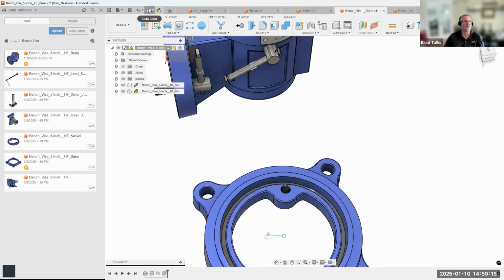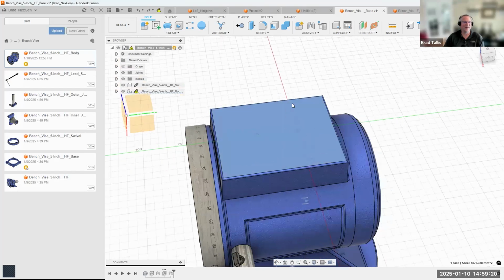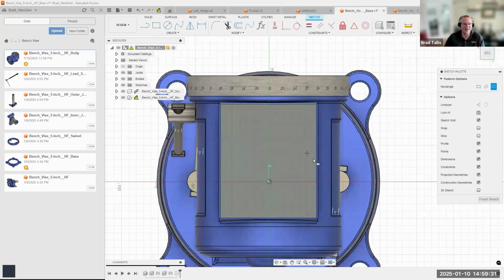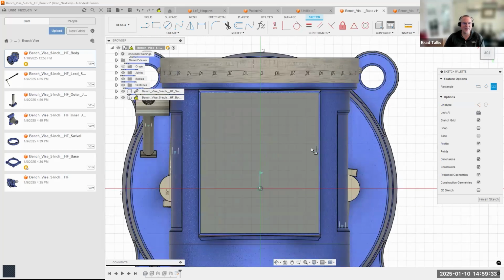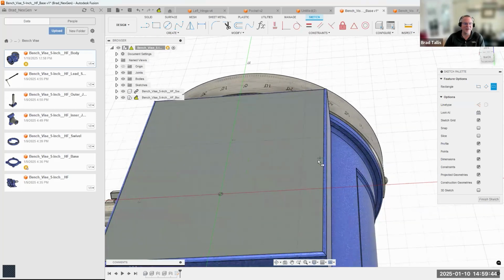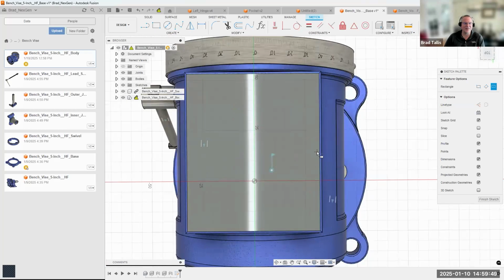Okay. So what I did is I created a sketch. And then when I said rectangle, I did what's called a center rectangle. And then if you hover over edges, you'll notice when I get near here, you can kind of see how it's catching to that edge. And right there, there's a little triangle. It's probably really hard to see. I wonder if I rotate in 3D, if you can see a little bit better. But it's creating what's called a snap guide.